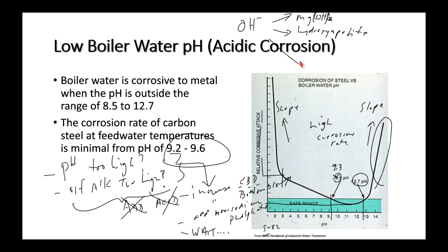Or if we do get any low pH, acidic water coming in, the low pH water will cause our hydroxide to fall. So if we wait long enough, the hydroxide, if it's not too far out of whack, will probably take care of itself.